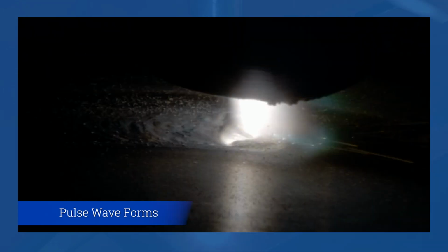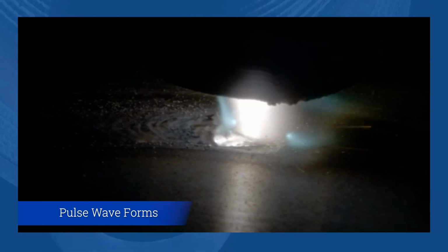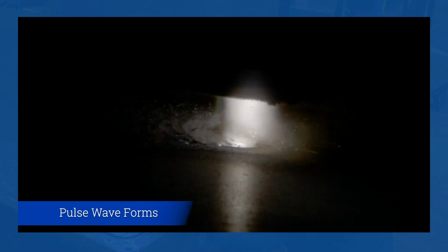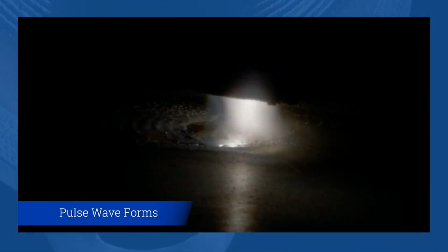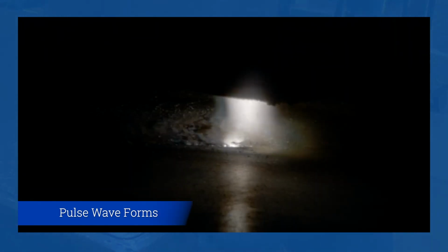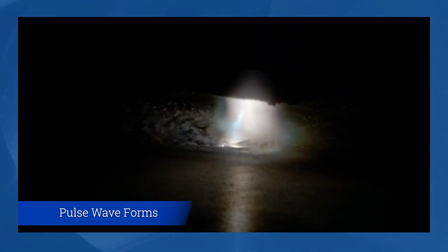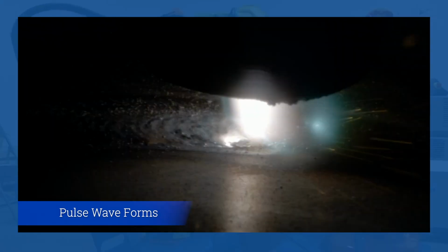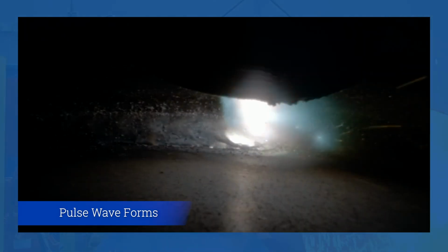I'm going to keep it simple. We're going to keep the background at 50% of the pulse peak, and we're keeping the pulse, background, and peak periods equal. So all we have to do is change the frequency so we get the same number of pulses per inch, and they need to be closely spaced, but the weld must freeze on the background of each pulse.